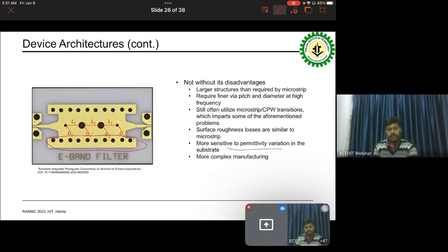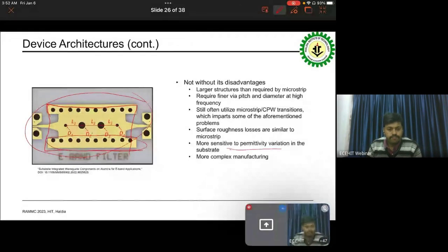Other than that, there is actually some benefit that I didn't mention, and a lot of that comes down to line width and fine line. Because this is basically just a big, simple conductor sandwich, there's not a lot of need, or any need in many cases, for any kind of tight line width control or tight gap spacing, which is going to be another big one. So we're not having to create these very tight, 25 micron gaps in between transmission lines, which is a big advantage of this.